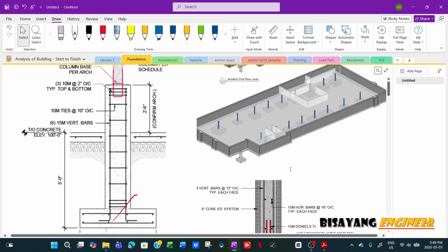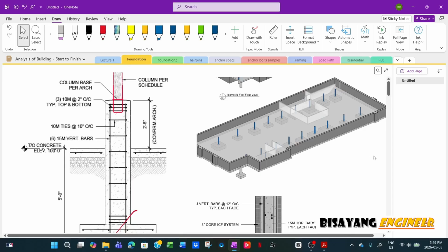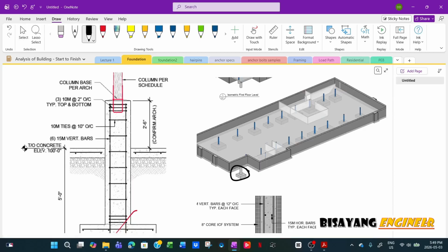Oh, by the way, this is just one of our projects. So this is the spread footing, and then this one, there's also spread footing. This is a basement, so there is no pilaster on this footing here. It's just the column directly on top of the footing. But this one is an entrance. There's a canopy. This pilaster supports the canopy above. And then it is of course the same depth as the basement footing. That's why we have that column, or pilaster.